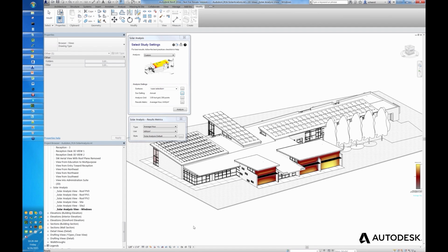Okay. The lighting analysis tool will consider those reflections, and that's available in the same place in Revit on your Analyze toolbar. Here's the solar analysis button, and these are the lighting analysis buttons. And there's a number of webinar recordings available on the lighting analysis tool. So you get the solar analysis plugin from Labs, and then it shows up here on the Analyze tab? That's right. Download the plugin from Labs, install it for your version of Revit, and it'll show up in the Analyze toolbar.